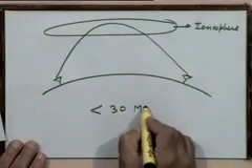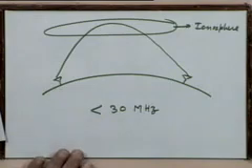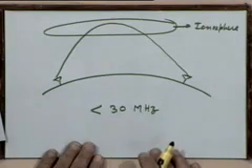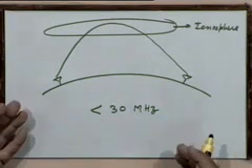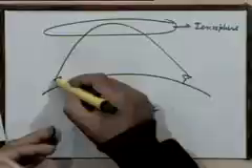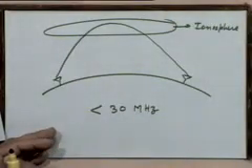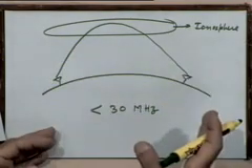Not for all high frequencies. It also has a limitation. The frequency must be less than about 30 megahertz or so, right? Maybe a little this way or that way, but around this range. If your frequencies are still higher than this, then the wave that you transmit from here will skip the ionosphere. They will go out of the earth. They will never come back.